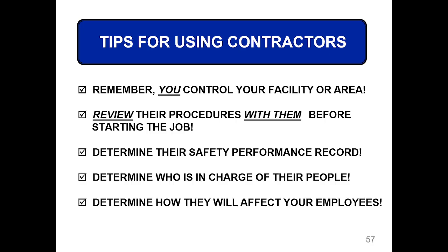If you require RAMs, you need a risk assessment and method statement. The risk assessment helps the contractors map out all the risks inherent in the tasks they're going to conduct. The method statement, like a job hazard analysis, shows how the work is supposed to be done.